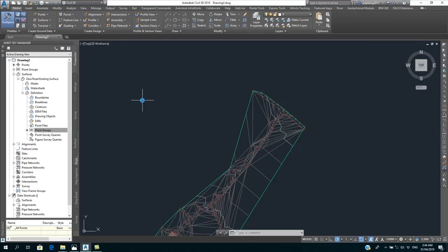So in this case, we are assuming that we're going to have a reference of our alignment to define the center alignment that's going to have a pavement structure of 3.65 as the normal for a single carriageway, and it's going to have the drainage infrastructure by the side. So that's what we're considering. So this central alignment will be the information to build our assembly and corridor. So it has to be referenced as such.